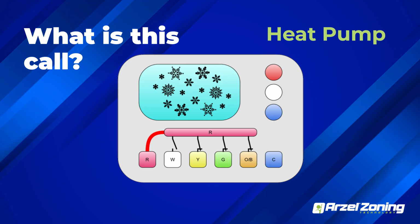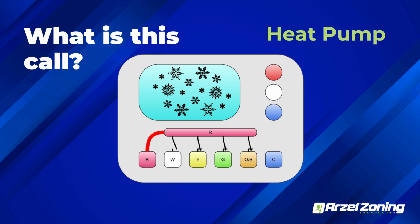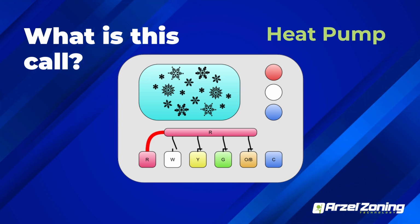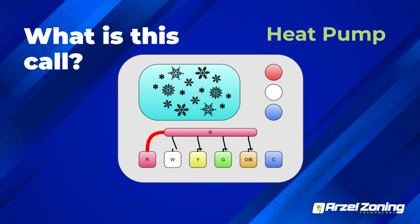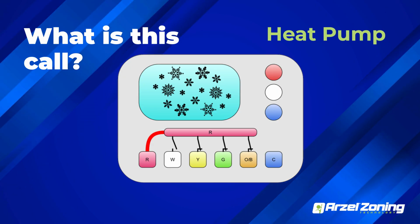So if you have the AirBoss or the MPS panel, the O terminal and the B terminal on your HVAC outputs are separated. So if you have the MPS or the AirBoss and you have a piece of equipment that energizes in heating, such as the Rheem Ruud, then your reversing valve wire from that equipment hooks up at the B terminal, B as in boy. However, the thermostat still has to energize that reversing valve on a call for cooling.